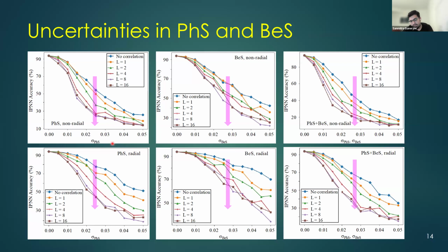If you have large correlated uncertainties, a huge fraction of your devices have variations in the same direction. Whereas with uncorrelated and highly randomized variations, there is a chance that variations between different MZIs can cancel out. So the main takeaway again is that we would rather have random variation than highly correlated systematic variation.